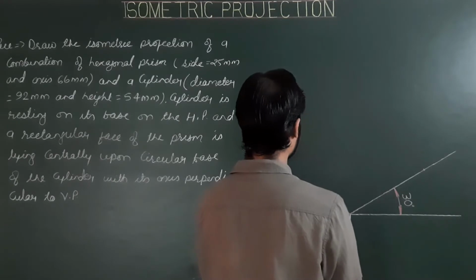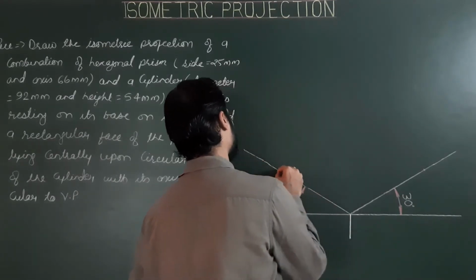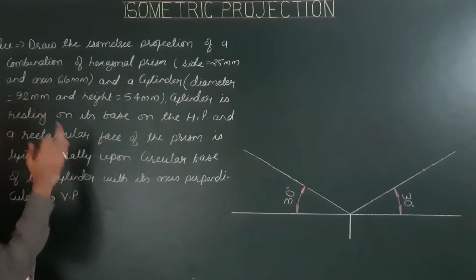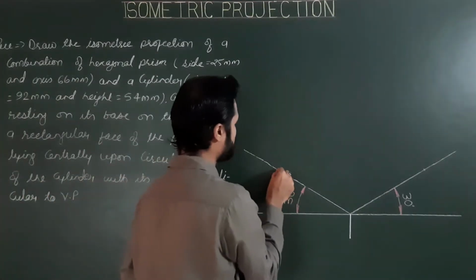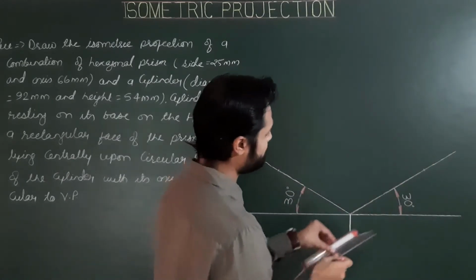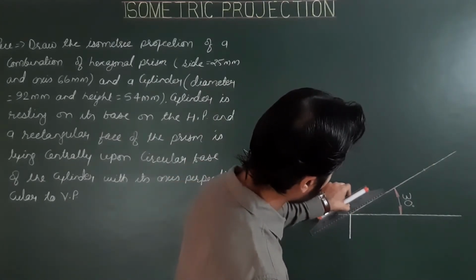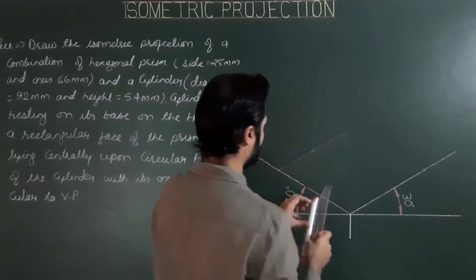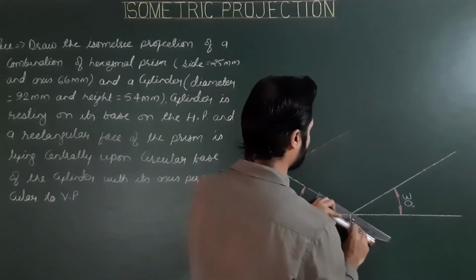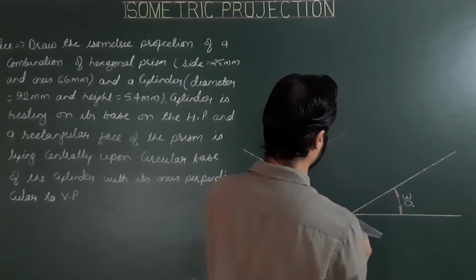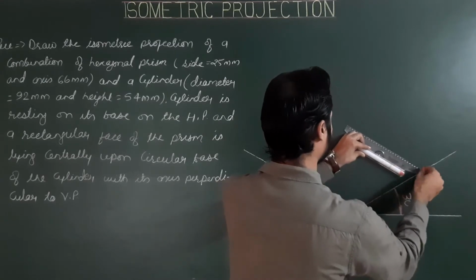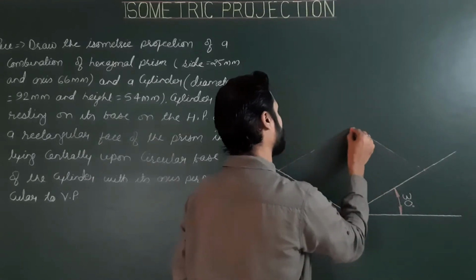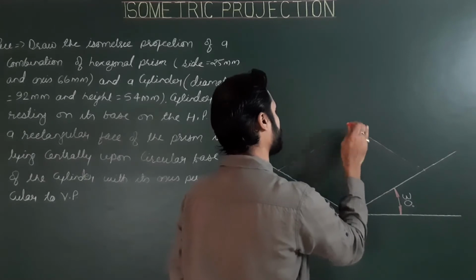You know the process. First, we are assuming that this circular base of diameter 92 is a part of a square, which is the helping figure or closing figure of the circular base, to be projected along first and second iso axis, and the diameter 92 is given to us.